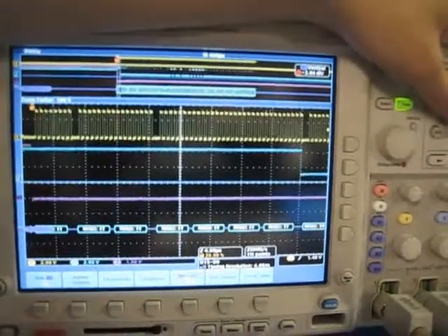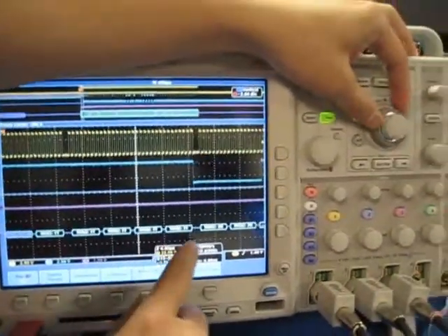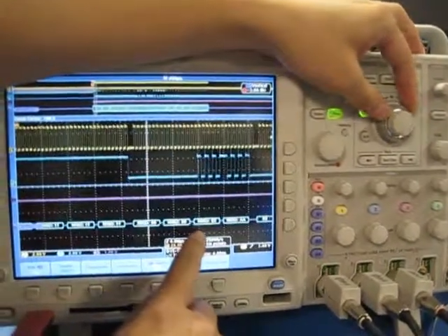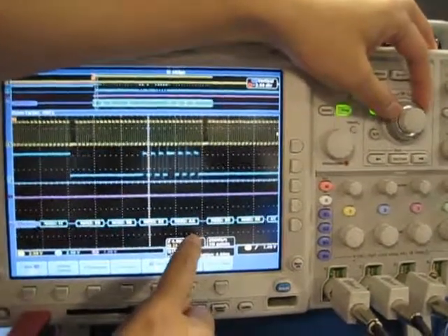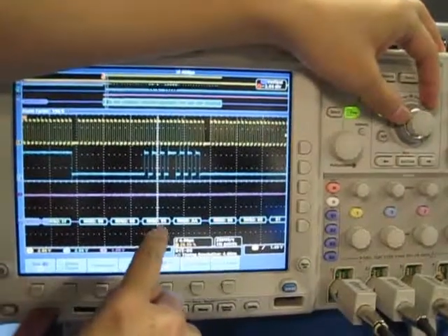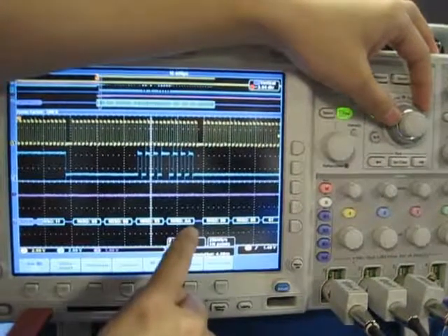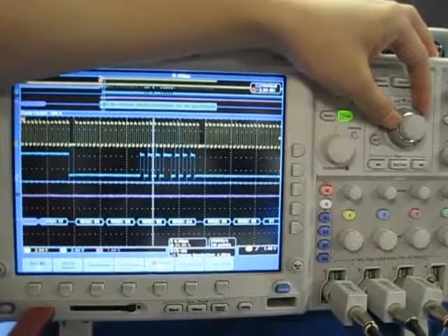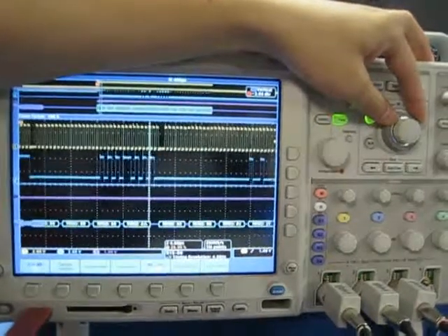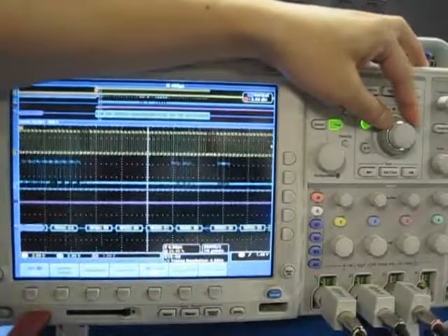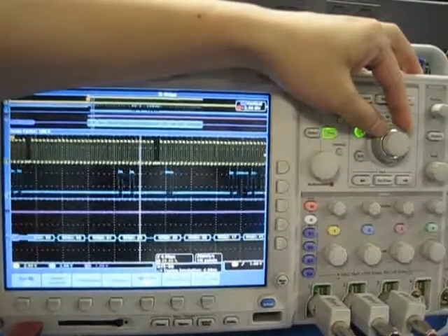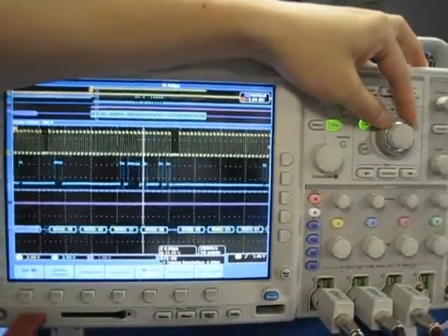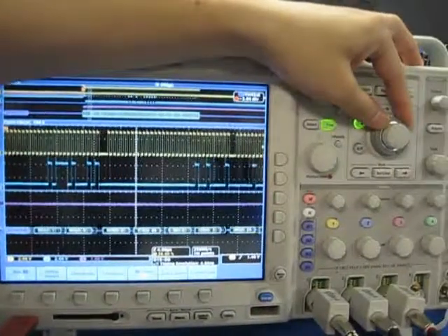We will see the really valuable tool: we can see all the decoded SPI data, like a protocol analyzer. Once we find 55 and AA, this is the booting initialize code. After that, the chip will initialize the whole internal peripherals and also initialize the memory.